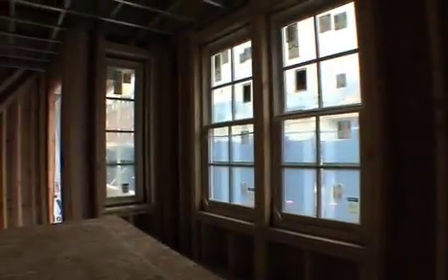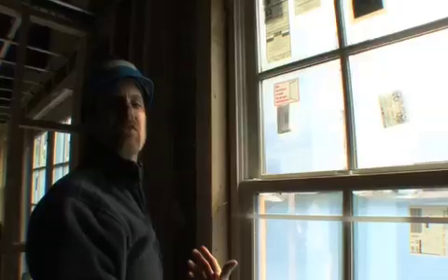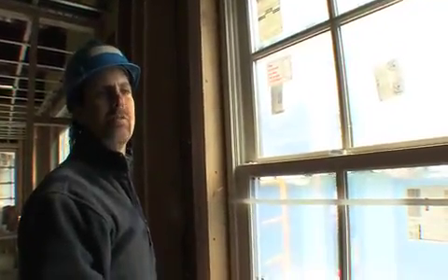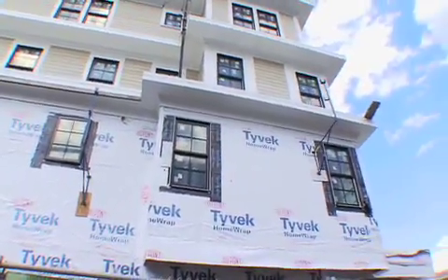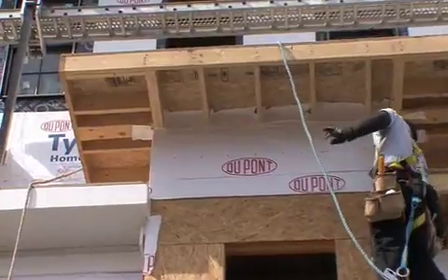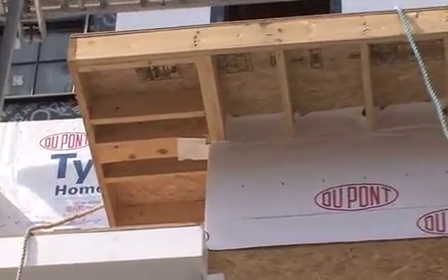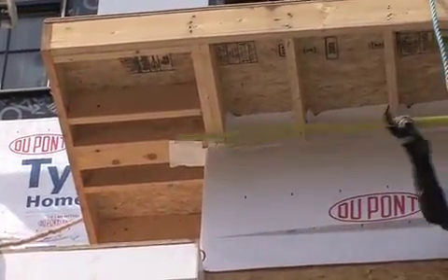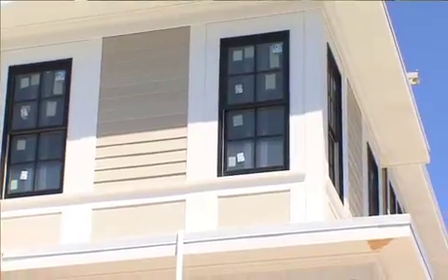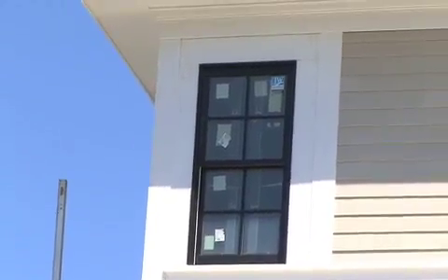So on the south and on the east and the west sides of the building in particular, where you get most of that solar gain in the summertime, this low solar heat gain coefficient will really help reduce the air conditioning loads. There are other ways to minimize the amount of solar heat gain radiated through windows. We also have shading overhangs built into the exterior of the building to provide approximately 50% of shading during the overheated periods of the summer.